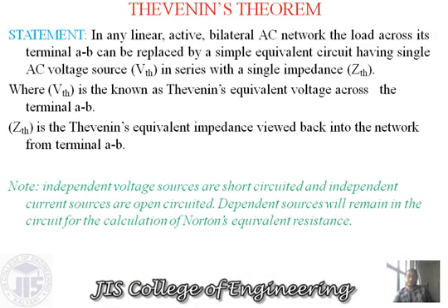So, for the Thevenin's theorem, as the statement was for the DC network theorem, the statement will be same. The same things will be there. Just in place of Thevenin resistance, there will be the Thevenin impedance. It means in the place of RTH, we will write ZTH, because we know in case of DC circuit, the resistances are there, and similarly in case of AC circuit, with the resistance there is another part that is called the reactance, and altogether this resistance and reactance is called the impedance. So we will write over here ZTH.